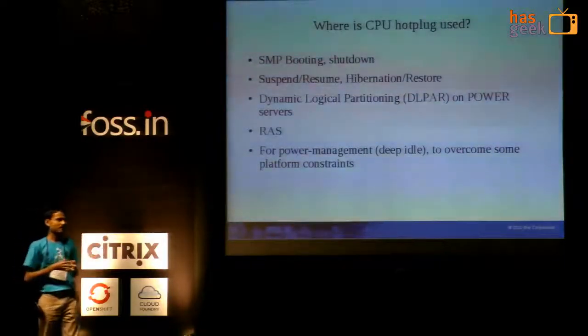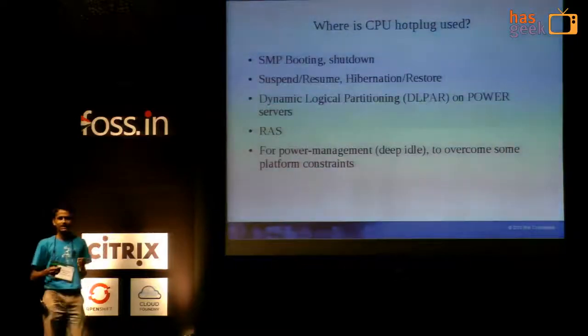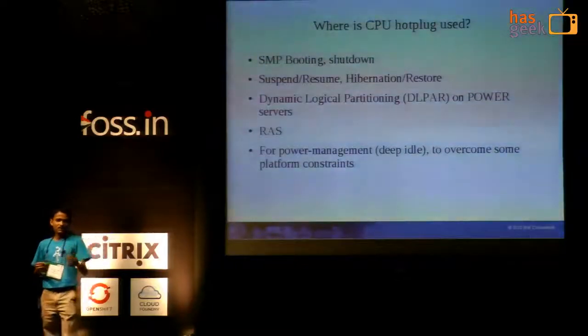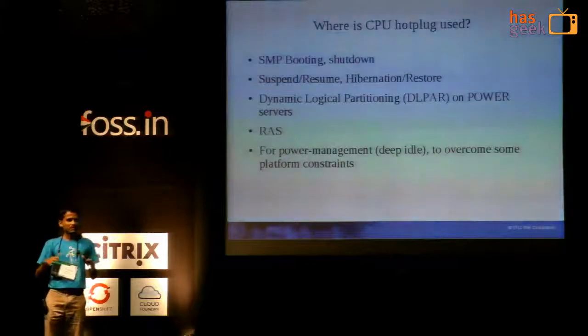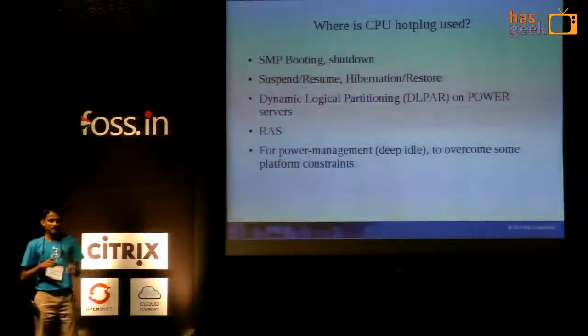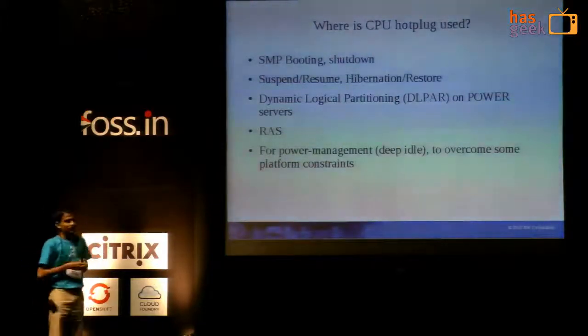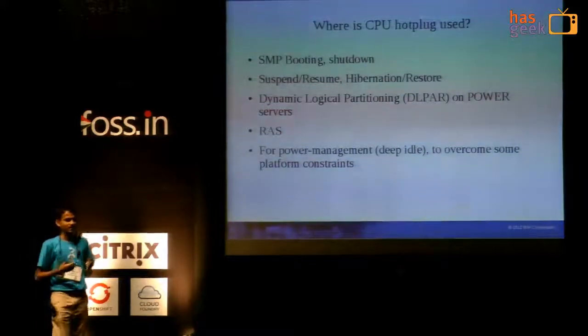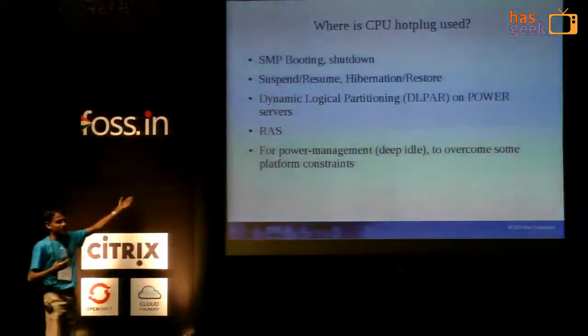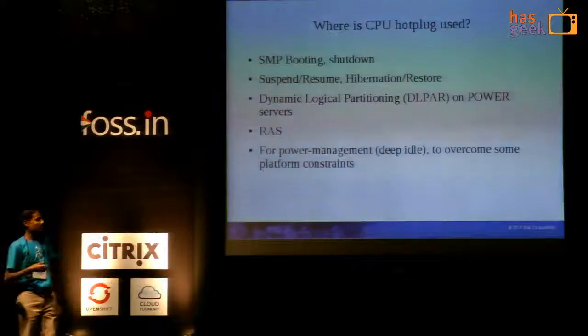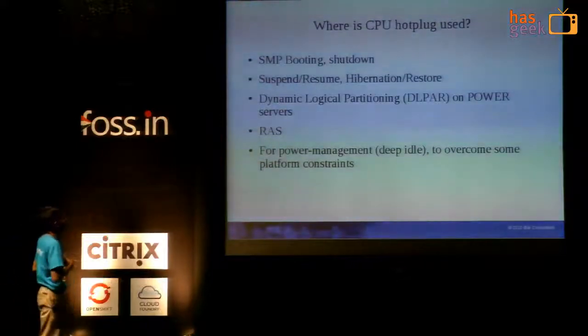The ACPI spec requires that the moment you are going to ask the firmware to put your system to low power state, there should be only one CPU which is active and the rest of the others should be with interrupts disabled and doing nothing. So there are some requirements. Even hibernation and restore uses the same logic. So basically you use CPU hot plug in these areas also.